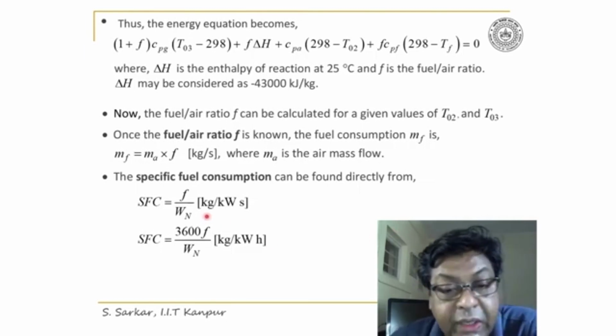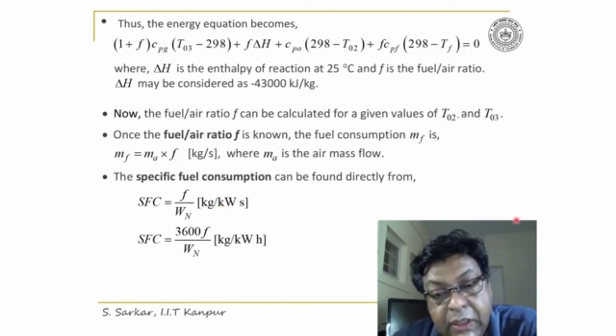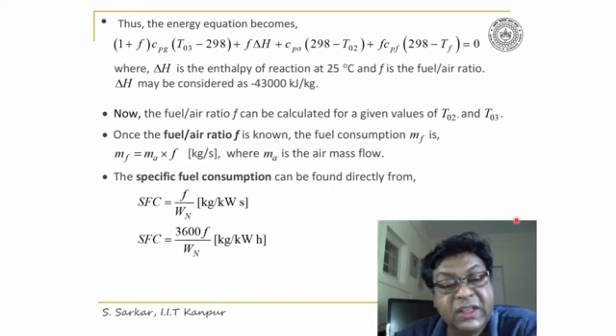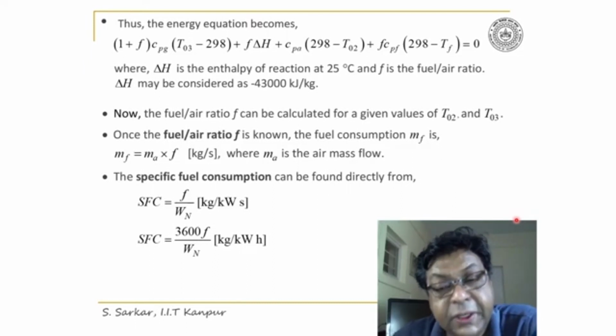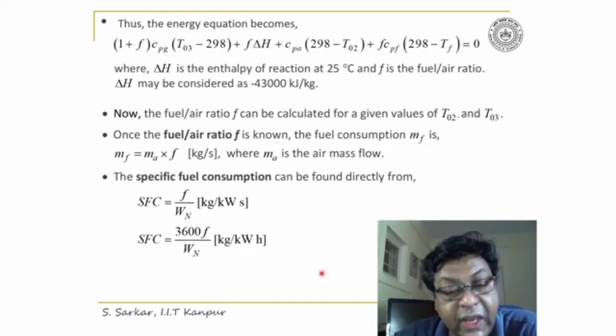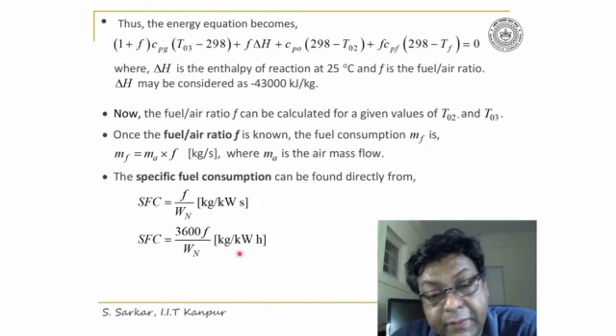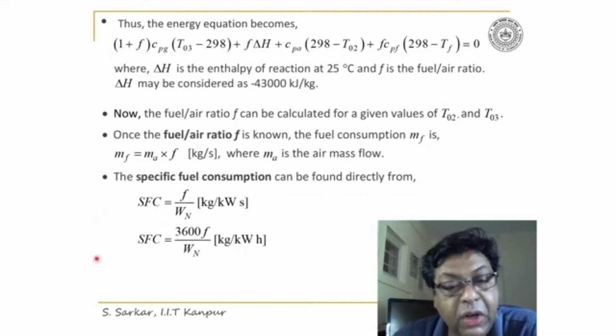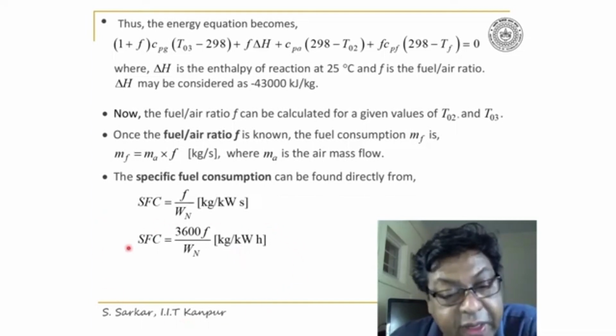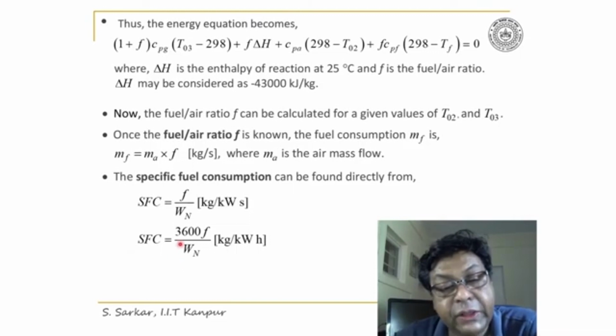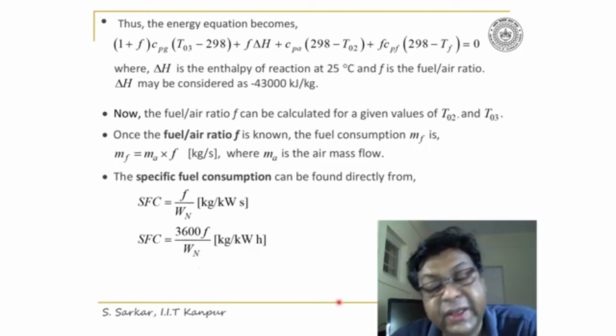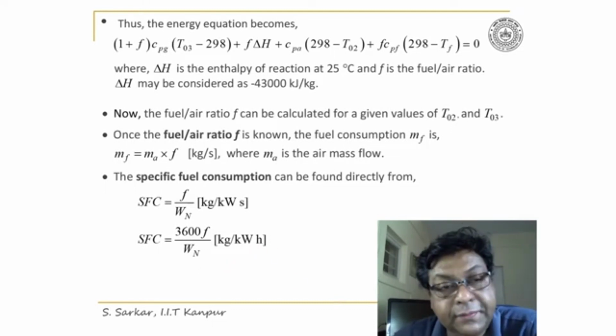Thus, the unit would be kg per kilowatt second. Generally, the specific fuel consumption is expressed in a unit of kg per kilowatt hour. Thus, SFC equals 3600 F divided by Wn, and the unit would be kg per kilowatt hour.